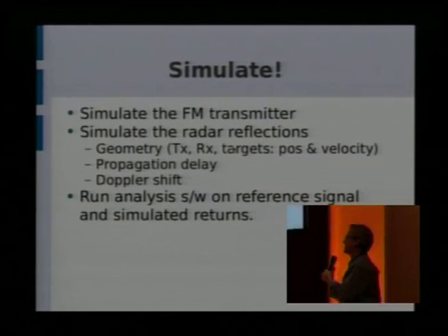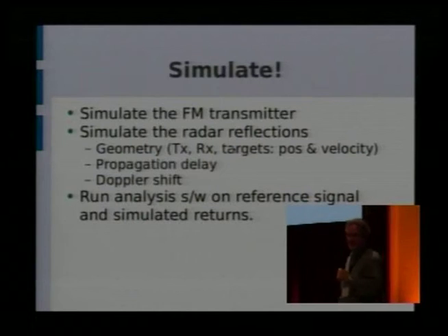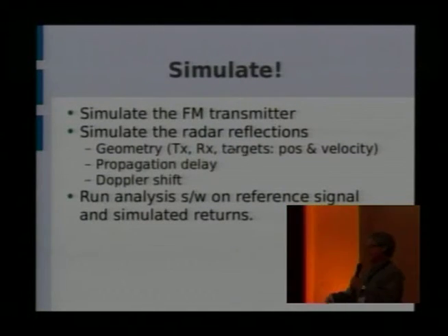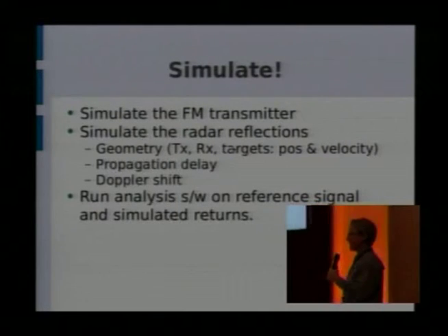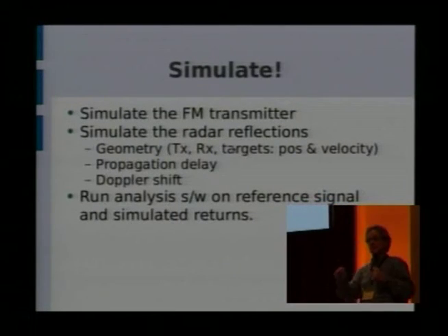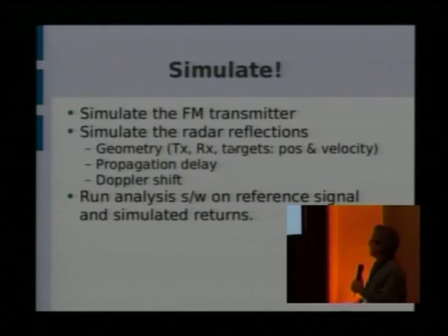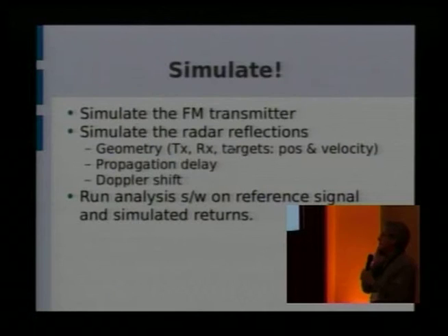I'm like, okay. So now we get out our GNU Radio toolbox. We have an FM transmitter in there. We got all kinds of stuff, but we got narrowband FM or wideband FM. So we say, okay, I got a random audio signal. I'm putting it into my transmitter, and instead of putting it on the air, I just put it into the disk. And then I say, okay, now we want to simulate radar reflections.